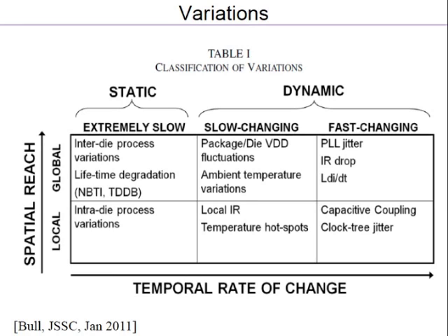So what that means, as a corollary, is if you want very good matching, you want to make sure you not only replicate the sizes, you replicate the layout, as well as you replicate the neighborhood. Because the neighborhood of the transistor affects, for example, the dopant. It bounces off perhaps things and falls in. Light, which sets up the pattern, diffracts. So everything has to be made identical if you want really good matching, which is required for analog applications, not for digital.